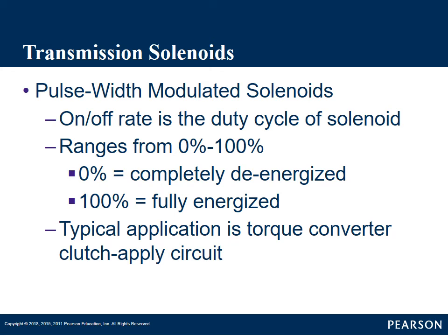Instead of the hydraulics of the throttle valve and the governor directly operating the valve, we can monitor vehicle speed and engine load, and adjust shift solenoids and pressure solenoids to control pressures in the transmission to get it to shift at certain speeds and RPM.